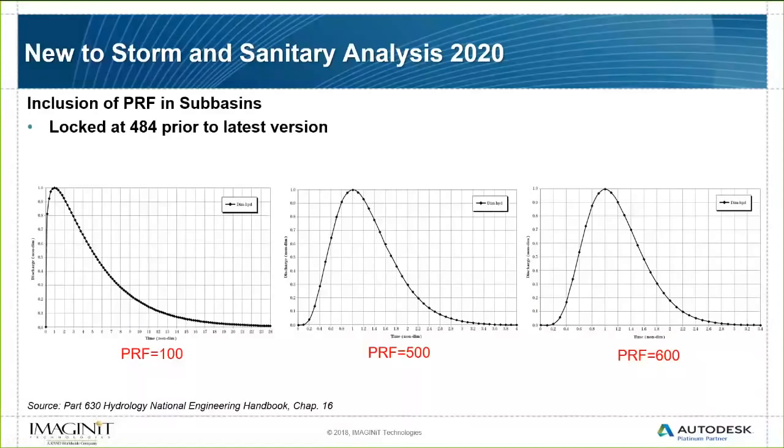I changed my surface so that first I was looking at a watershed analysis, then I broke down that watershed analysis boundary. I turned on slope arrows in my surface, figured out which way it was going to flow, and then drew a polyline as a boundary and used it as the boundary of my catchment. Now, if you're asking whether you can change the geometry after it's a catchment object,